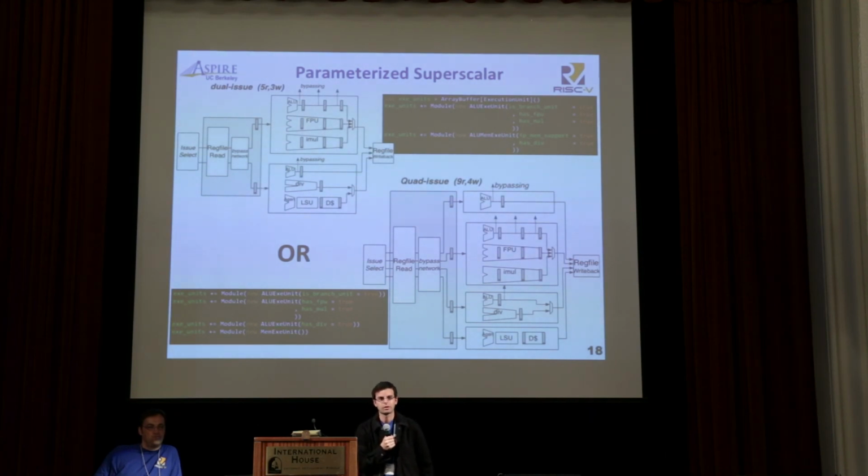The issue scheduler is parameterized. You can change between an age-ordered collapsing queue or an unordered R10K design. So if you find that you paid for something in one area, you can change a parameter to compensate in another area. But yeah, the clock frequency is going to be different between different designs, depending upon how aggressive you are.